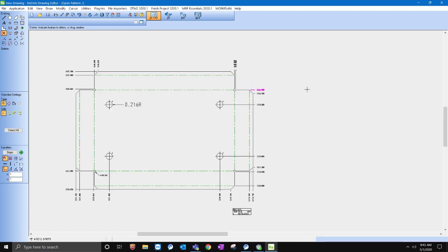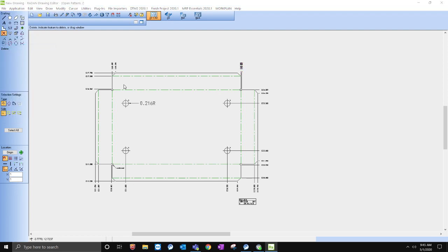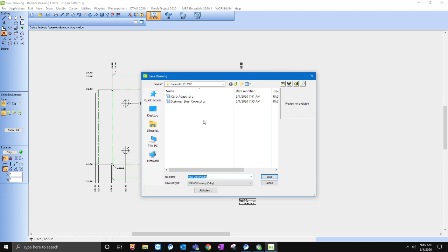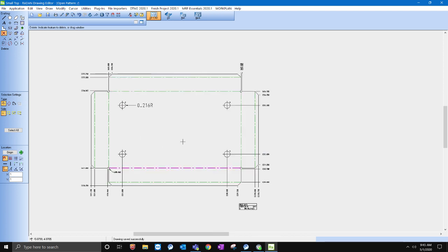Also, if I come up here, you can do automatic dimensioning, and you can select what you want to do on the auto dimension and hit apply, and it'll go ahead, do that, and it's given me a whole pattern here. So I can put my whole pattern down there, and because I automatically dimensioned everything else, I'll just get rid of this, right? So there's my drawing.